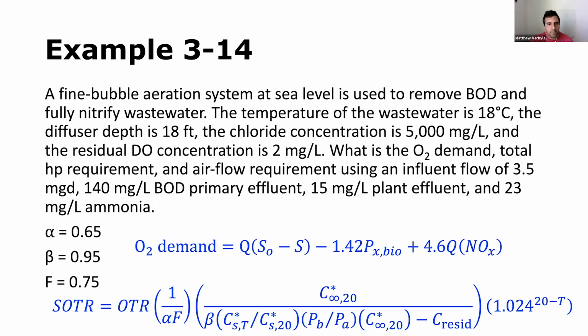What is the oxygen demand? What's the total horsepower requirement? And how much airflow do we need if the influent wastewater flow rate concentration is 140 milligrams per liter primary effluent, so that's the concentration coming into the aeration basin.